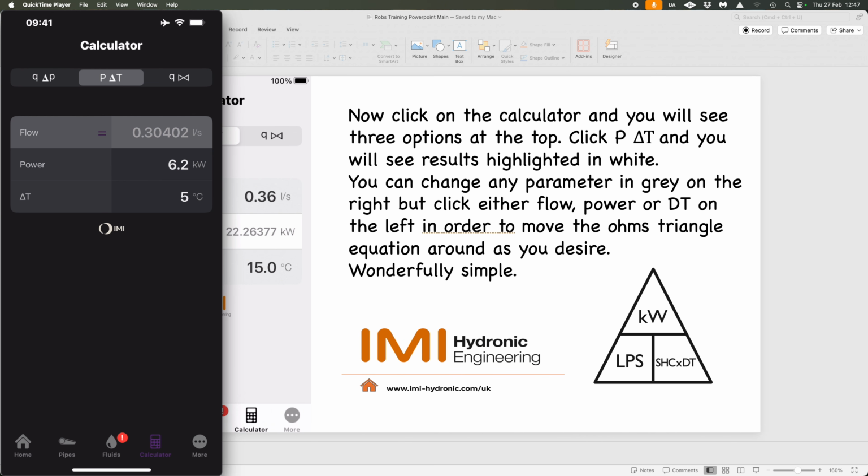So if you start looking into the reasons behind this, this can actually state that a lot of the existing pipework within that property will probably be exactly the right size, if somebody sized it correctly beforehand. And we do know in the UK that we are very, very prone to oversizing pretty much everything, from boilers to heat pumps to pipework and all sorts of things like that.